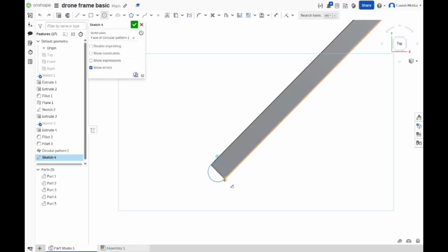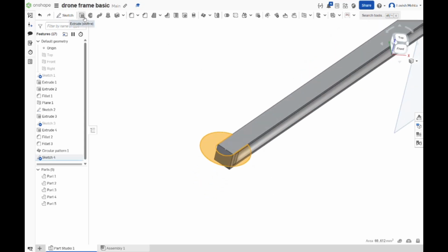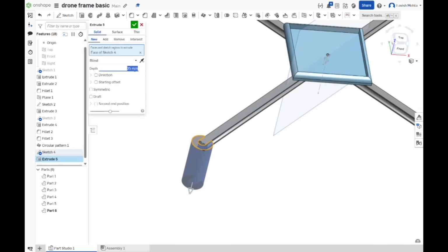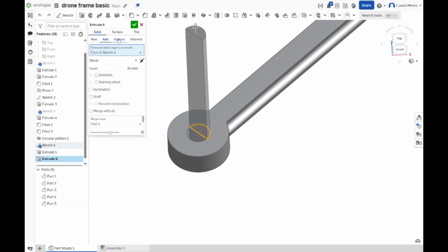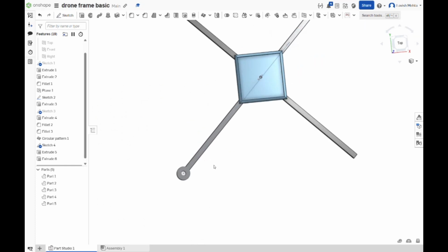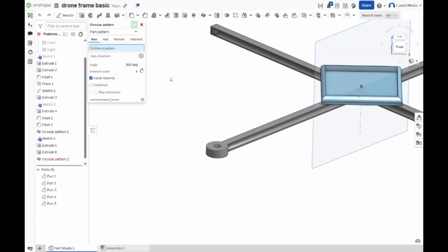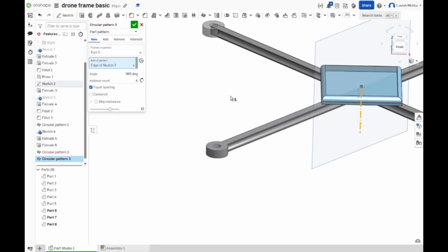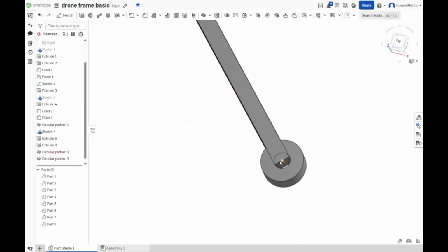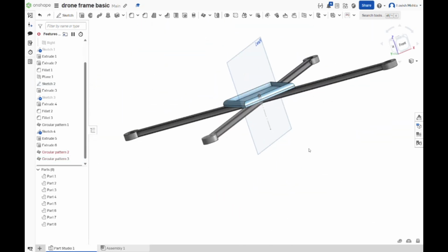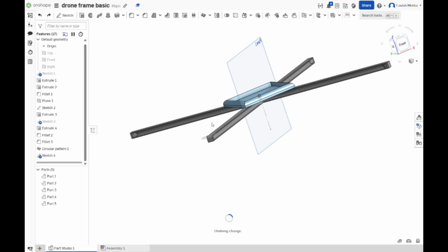Now for making the motor hub, the techniques remain the same: you import a sketch on a particular plane, extrude it, and then depending on whether you want to add or join them. I'm not going to demonstrate exactly which motor hub you have to use, because toy quadcopters have different configurations, either having simple motors directly attached or gear assemblies. But since the overall construction methods remain the same, with circular patterns for these things, I'm just removing all of these by clicking Ctrl Z.